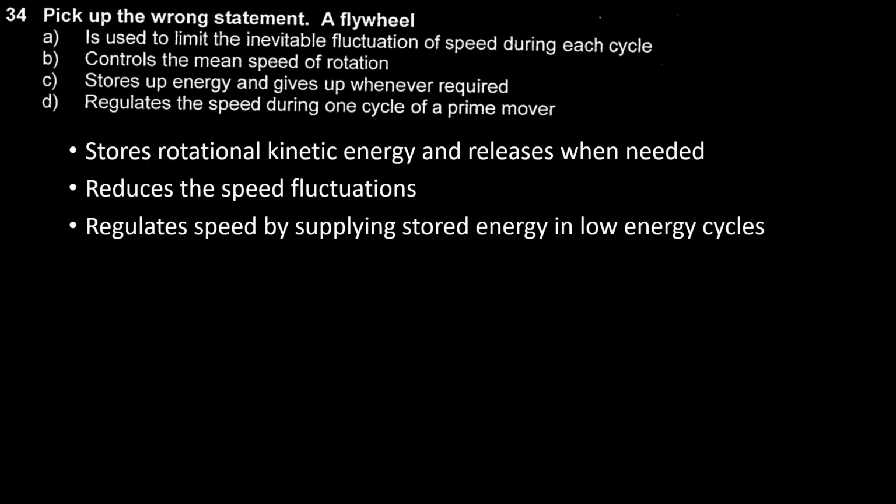Next question. Pick up the wrong statement about flywheel. A flywheel is a mechanical device that stores rotational kinetic energy and releases it whenever needed. It reduces the speed fluctuations and regulates the speed by supplying stored energy in low energy cycles. So, the wrong statement is that it controls the mean speed of rotation. A flywheel is not at all used to control the mean speed of rotation. So, option B is the correct answer.